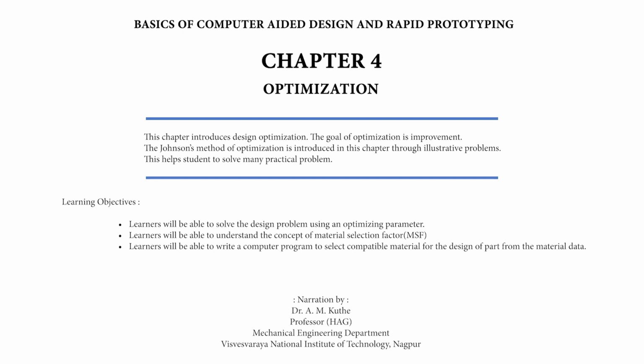The diameter d lies between d min and d max. This is a desirable case and no modification in the value of the diameter is required. The diameter d is greater than d max. In such a case, the material is rejected because it is not compatible for the design. Based on the above, a table can be drawn where serial number, material, Sy, equation for d, d modified, and remark are the columns, and the rows can be filled by using the values from the material.